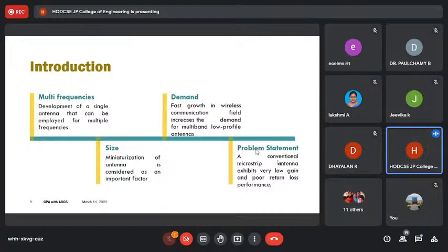The slotted patch and metamaterial ring designs are complex in nature. The long size of the array antenna used for multiband operation is a major hurdle for its widespread applications. In this paper, a defected ground structure is used for achieving multifunctionality with high performance.